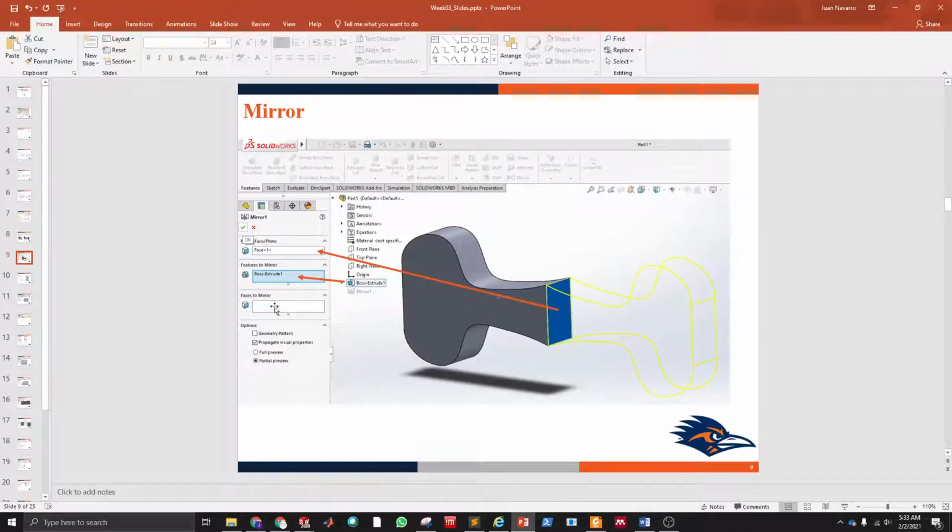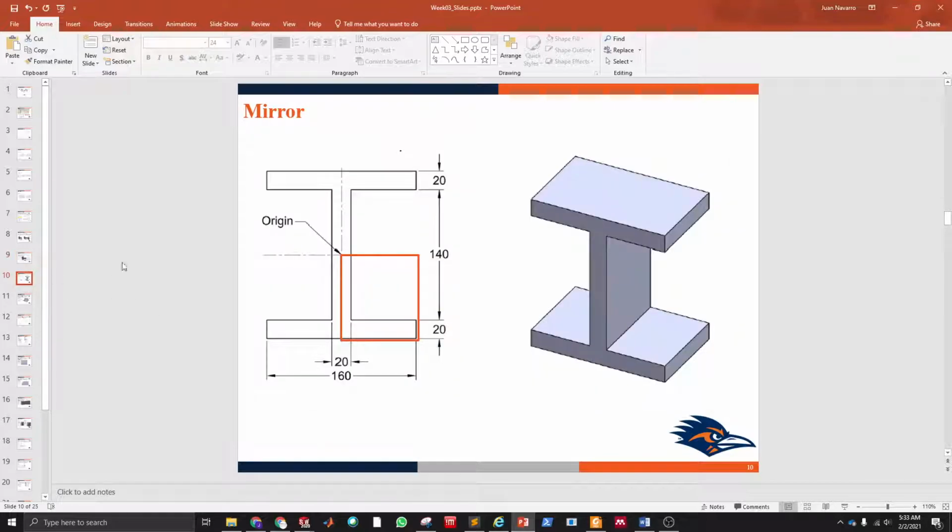Here I'm just explaining the different steps to do a mirror pattern. For example, in this geometry, instead of doing the whole eye, let's suppose this is a beam, I can just model 1/4 of that, and then I can use this horizontal symmetry and also the vertical symmetry, using the horizontal line and the vertical line to create the whole profile.